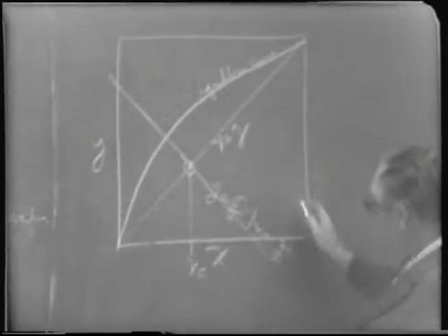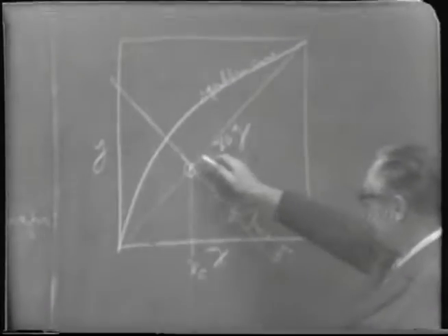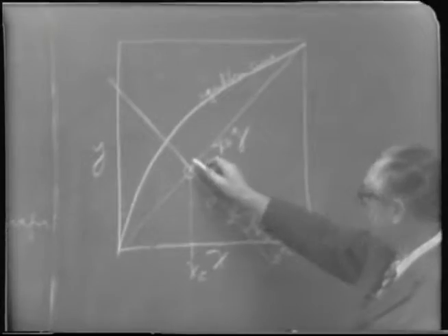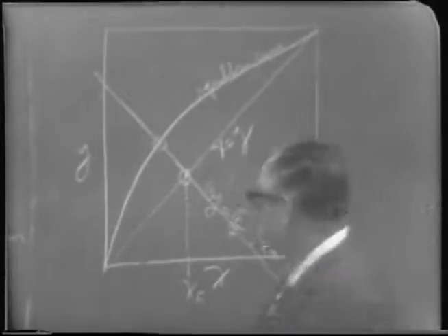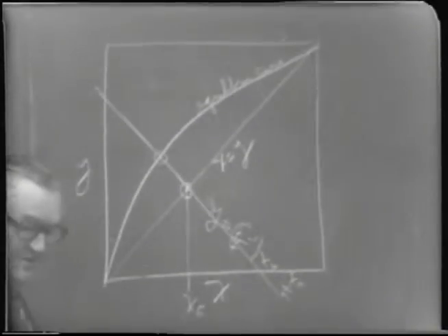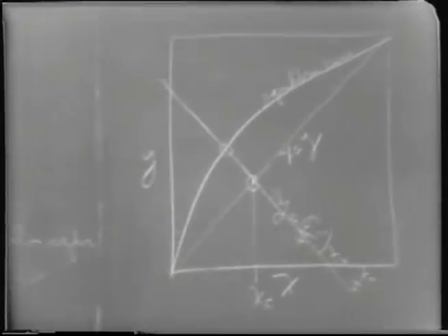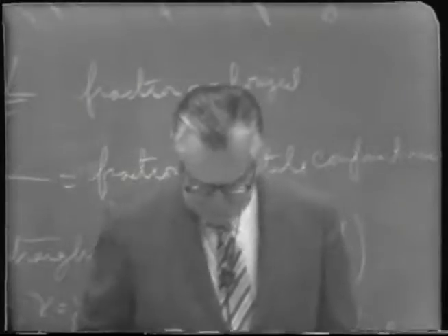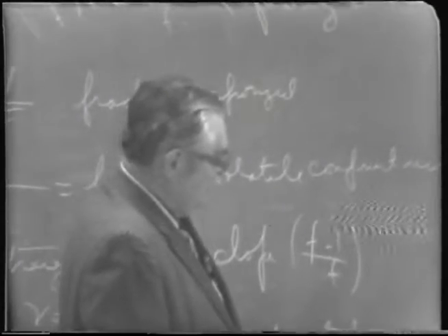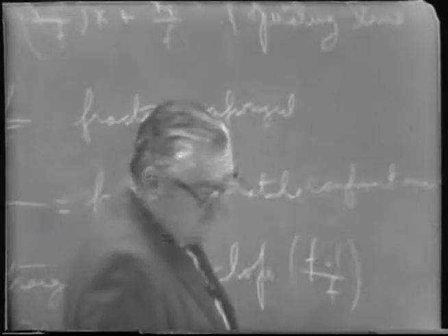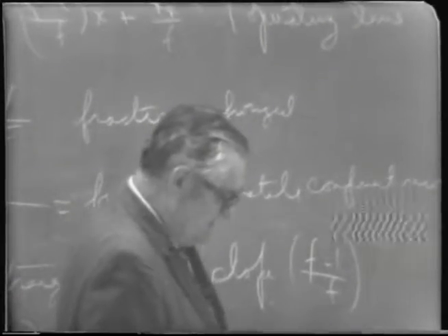There's one condition, condition 2 here, and the straight line which represents the process conditions represents the second condition. And so for a particular situation, the values of y and x would be given by the intercept of the two relationships. The intercept of this operating line with the equilibrium curve. Now this would be the more general way of applying this principle to the solution of problems.